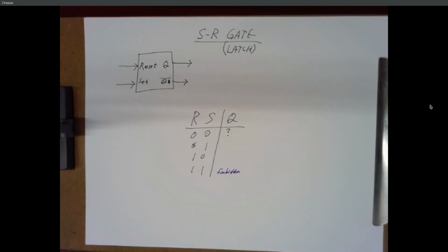That's something you're going to want to remember on, I think, two labs from now. You're going to be building something, and you're going to need a bunch of inverters, and you can fake an inverter like that. If you want an LED to light up when the output is 0, you can either run it through an inverter and then put it through an LED as usual, or you can just wire the LED backwards. Then when your output's 0, VCC flows through it, and the LED lights up.